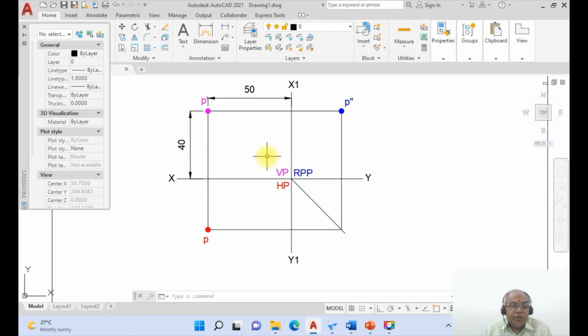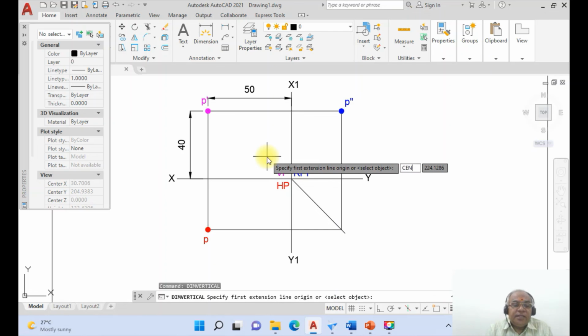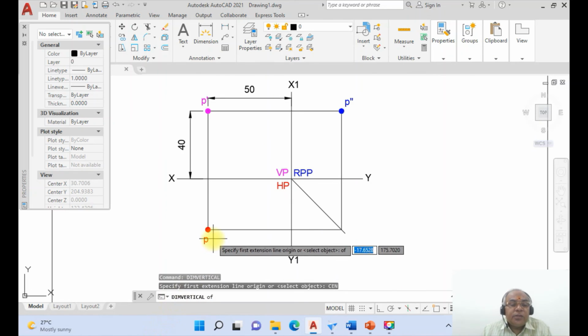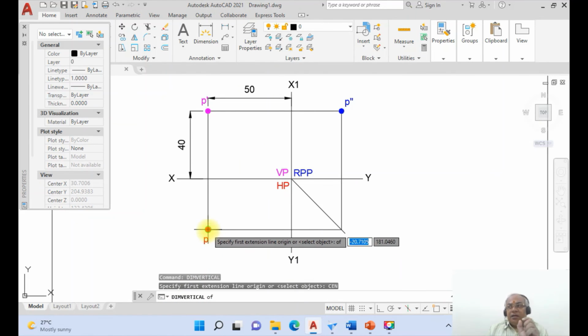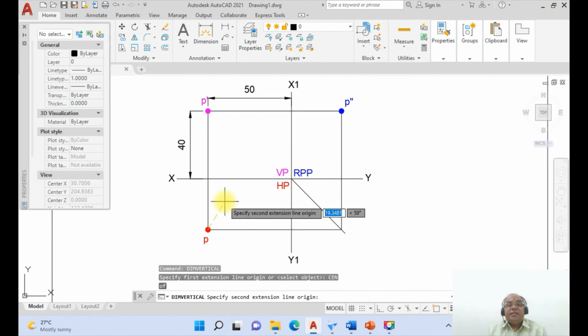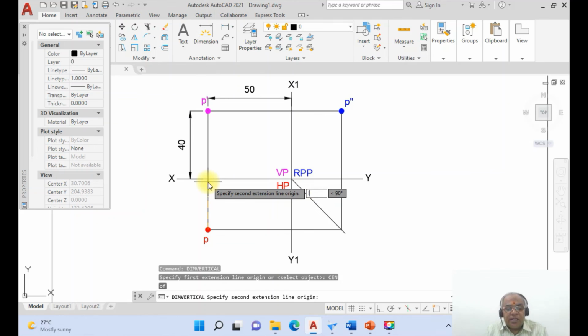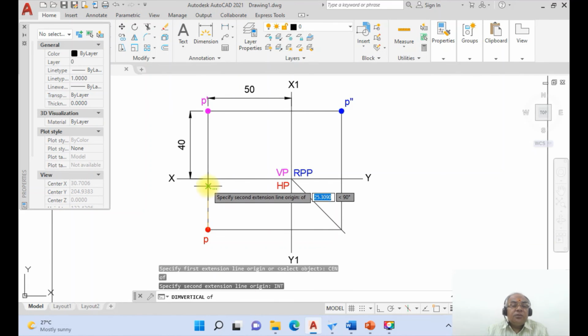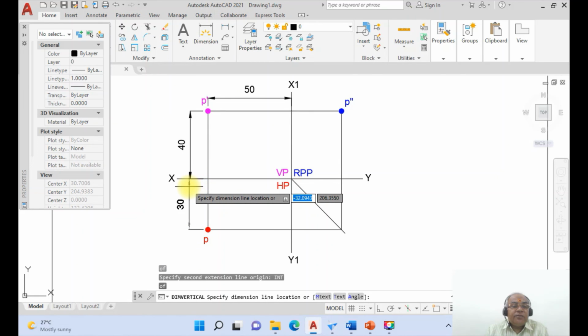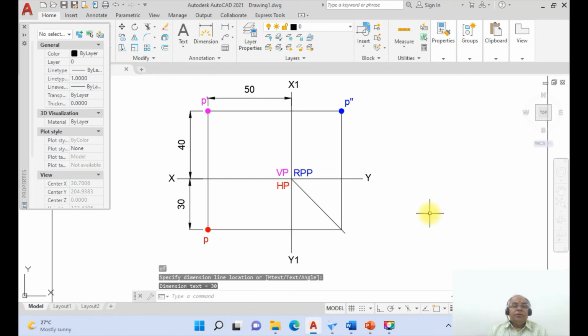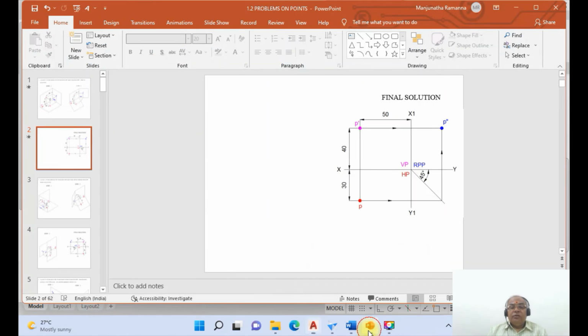Again you just go to dim vertical, enter. Because you have the donut, and a donut is nothing but the circle center, obviously you're going to take it as center and then take the intersection point. So these are all the snapping entities. That is the OSnap command. Take the intersection point, select wherever you want and click the first button of the mouse. So you are going to get 30. So this is all. You will be able to mark the dimensions of these two.